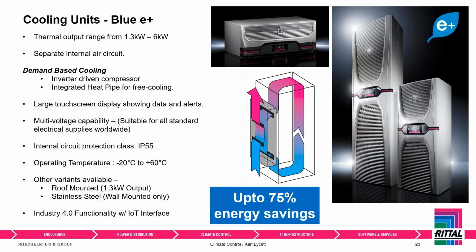And what that means for you is now it's gone past 0 degrees. This cooling unit, these Bluey Plus, can be used outside. They can be used outside with the caveat that they must be protected from direct rain. And you might think, well, I don't need cooling outside, but that is where you might be wrong, because a lot of sites might have, say, big water pumps and things like that in enclosures outside. It might be the depths of winter, it might be -10 outside, but believe you me, inside that enclosure, that pump is going full chat, and it's whacking out 3 kilowatts of heat. That heat needs to be gotten rid of.